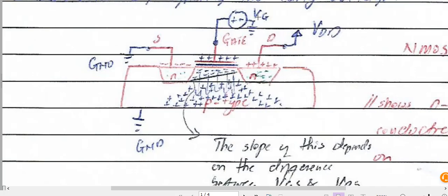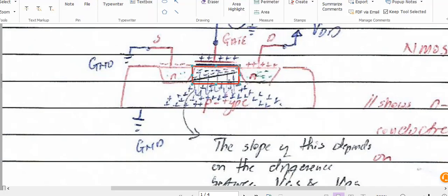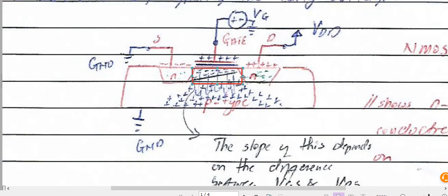Now, Vg and VDS, just like I've mentioned here, have different polarities. Basically, from this point to this point, there is a polarity gradient. What I'm trying to say is that on this side there's going to be a positive gradient, and on the left-hand side, there's going to be a negative gradient, since this part is connected to the negative terminal and this to the positive terminal. But we know our gate all over this whole region is positive.